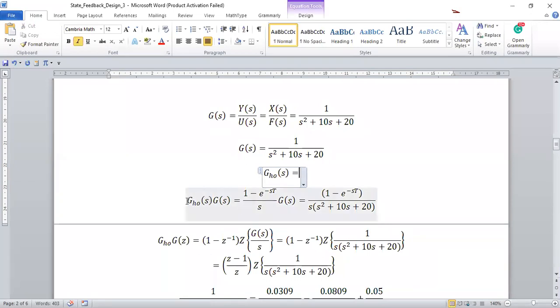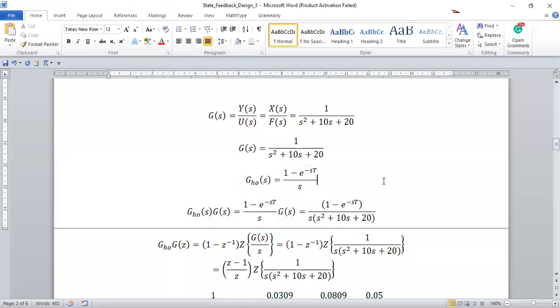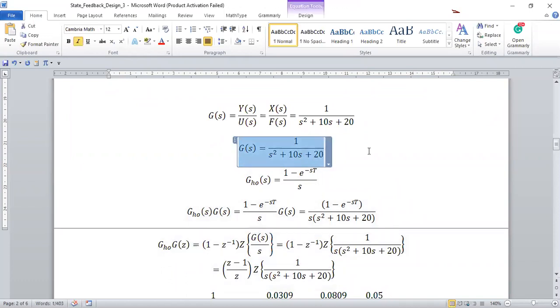This is the transfer function for the zero order hold. But in the last class, we just used this particular transfer function and converted it directly into the Z domain, which is not appropriate, because in the computer you have ADC and DAC converters. As a result of the influence of these converters, this is not really the transfer function the computer is seeing.